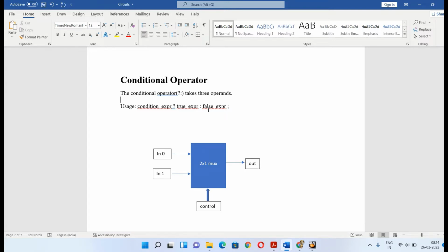The conditional expression is first evaluated. If the result is true, then the true expression is evaluated. If the result is false, then the false expression is evaluated. If the result is ambiguous, then both true and false expressions are evaluated and the results are compared bit by bit, returning x for each bit position where they are different, and the value of the bit where they are the same. Conditional operators are frequently used in dataflow modeling to model conditional assignment, and the conditional expression acts as a switching control.